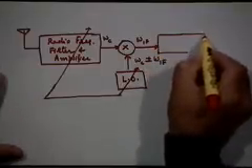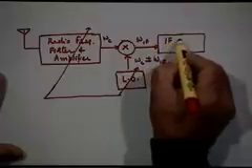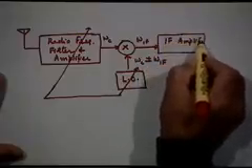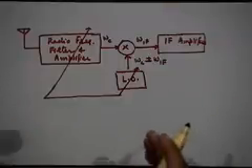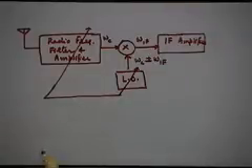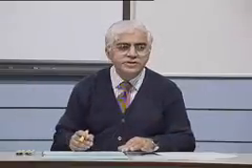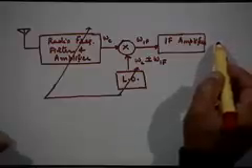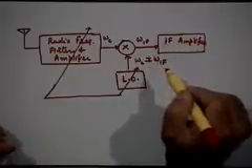So this is now passed through an IF amplifier, right, and it is this amplifier which provides all the nice properties that you want from the receiver. You can make it frequency selective, its bandwidth can be exactly 15 kilohertz, no more no less. Typically if you are providing for a bandwidth of 15 kilohertz in a radio receiver, the different transmitting stations would have frequency separation of about 20 or 25 kilohertz, right. So you want to make sure that an adjacent signal which may be 25 kilohertz away is rejected at the input of the IF amplifier. So that kind of selectivity can be provided by the IF amplifier.